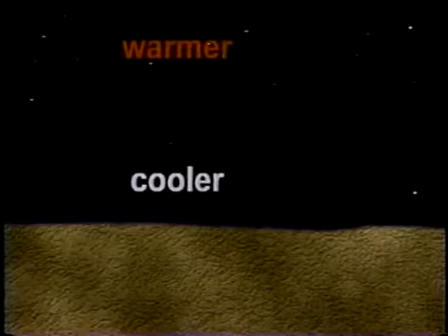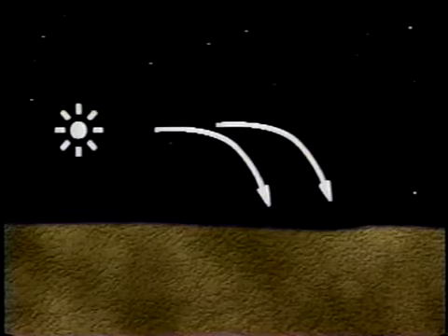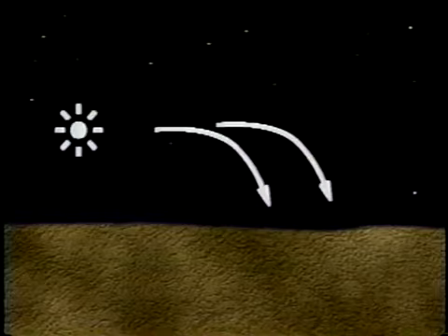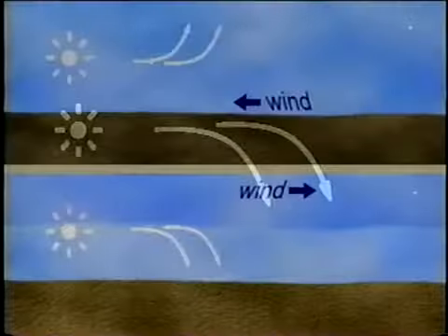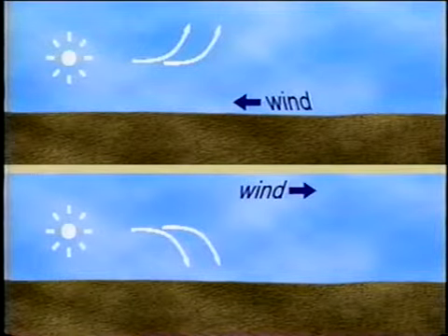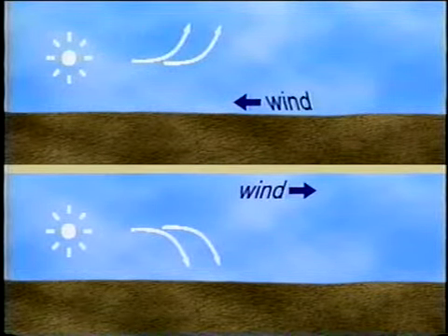At night, the ground usually cools by radiation faster than the surrounding atmosphere, thus causing the air temperature to become warmer with increasing height. This is called a temperature inversion. Under these conditions, the sound rays bend downward toward the earth. For this case, the noise level increases at the receiver. Besides the refraction due to temperature gradients, wind can also cause the sound to deviate from a straight path.